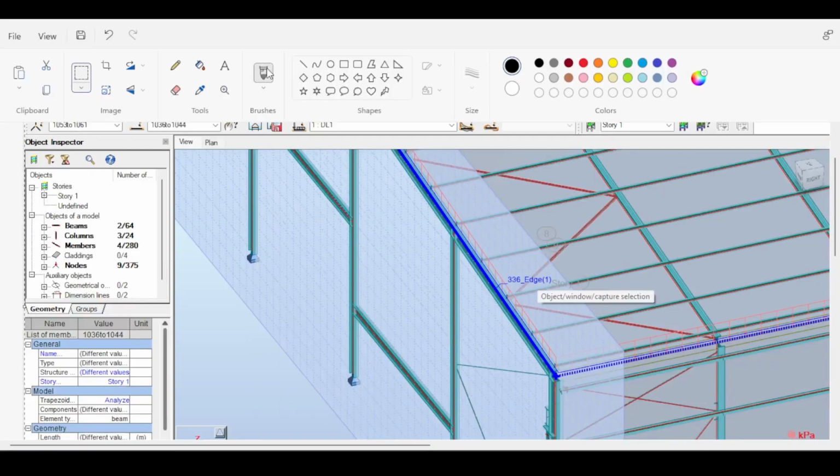Okay, so using paint now, this is a print screen. Using paint, you have pressures from wind attacking this side. I'm going to take this column as an example. And there is a portal frame which acts as a reaction to the wind load here. And of course, you have the support down here. Now, this reaction will cause pressure on the portal frame. This will lead it to bend in this direction and also to transfer the compression force here through the purlin to the bracing. Like you see how much you are affecting the structure.